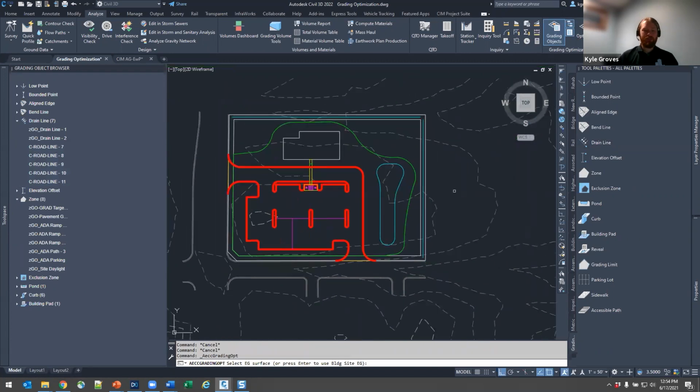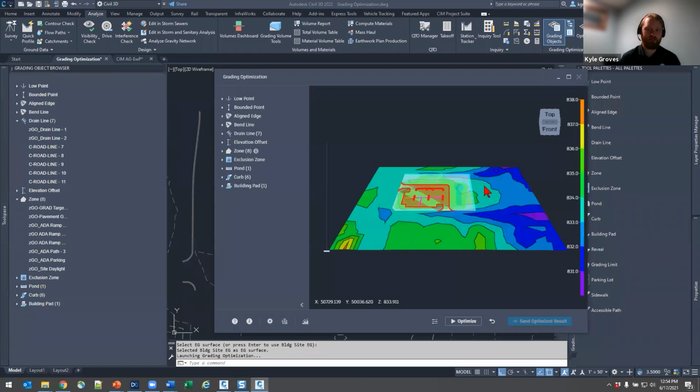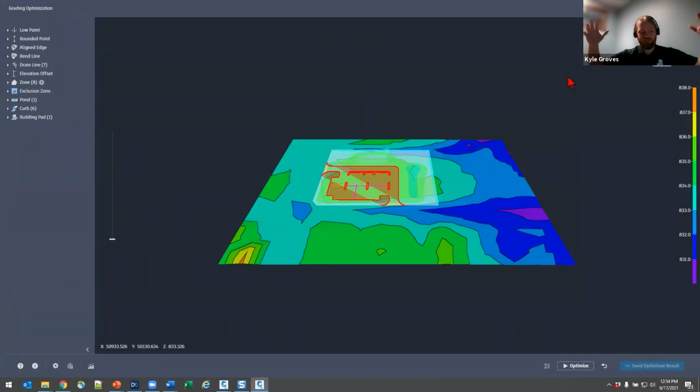When you do this, it's going to make you select an existing surface. It doesn't have to be existing, strictly speaking, but what are you going to be comparing your site balance to? In Autodesk's big long presentation on this, they do it twice. They take a random greenfield site and mass grade it flat-ish. Then they come through a second time and put up their big box Costco warehouse type place.